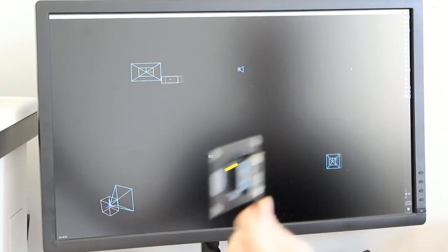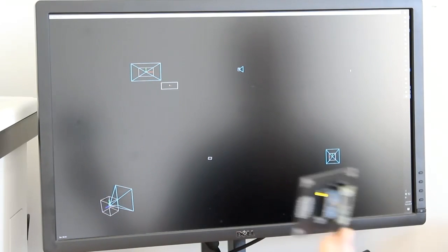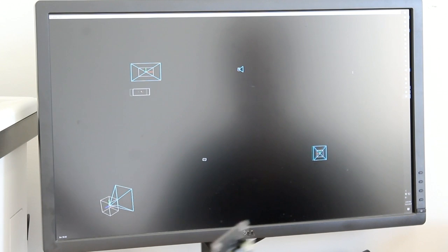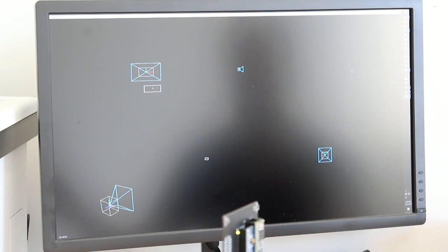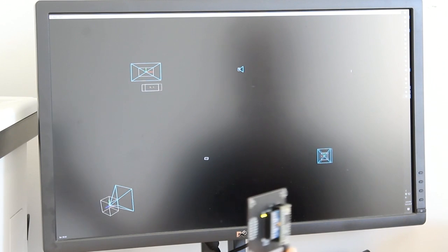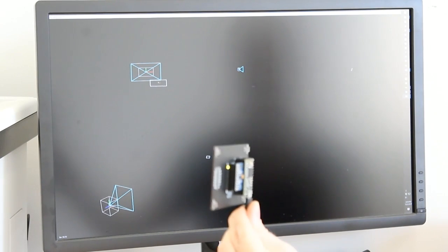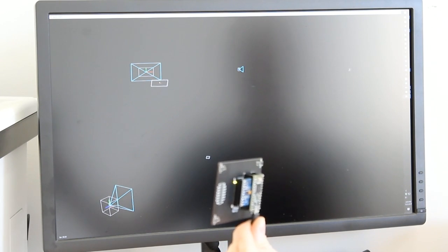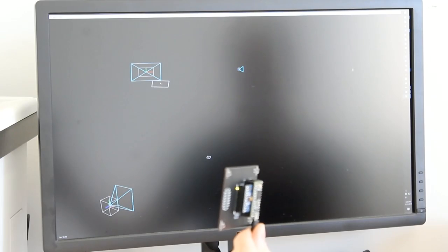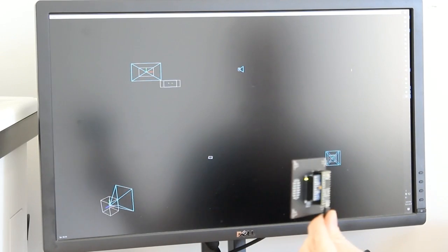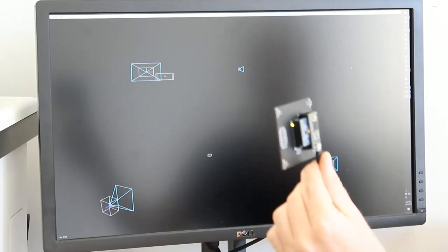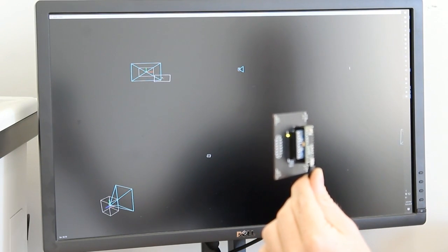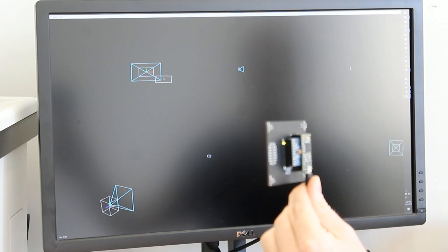Right, so it works quite well in XY, as you can see. So I'm just moving the Arduino up and down. There's a little bit of latency in here, mostly from the temporal filtering. The difficult part is really to get the Z coordinate right, because from these 4 photodiodes, it's going to be quite noisy, right? So now I'm actually enabling the orientation. I said that I can also extract the orientation from the homography matrix, and you saw that that was very noisy. So it's almost not usable at all. So you really want to use the orientation from the IMU or do some kind of a sensor fusion. Here you can see that it's going to be very, very noisy.